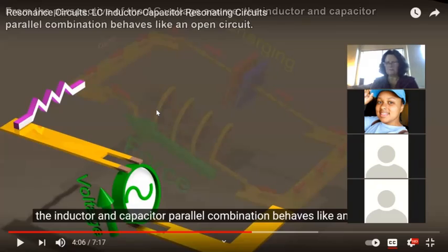So this AC source is getting bigger, so that's going into the LC circuit, and it resonates and filters out the other frequencies, and it's getting a little bit bigger on the input, so that input goes into the amplifier, and then the output gets even bigger. And then that gets fed back into the AC source. There's a limit based upon what your voltage power supply is. Yes, oscillators are sort of black magic, but they do work. And we'll talk about what causes them as we move along.